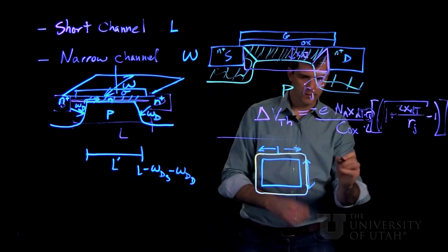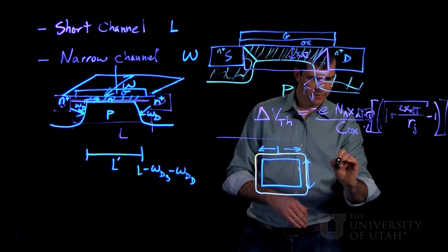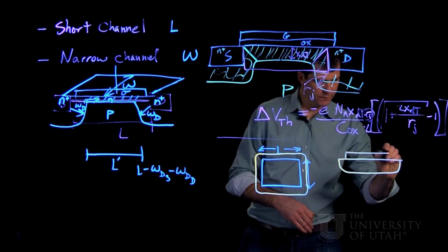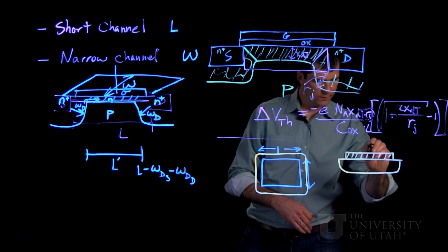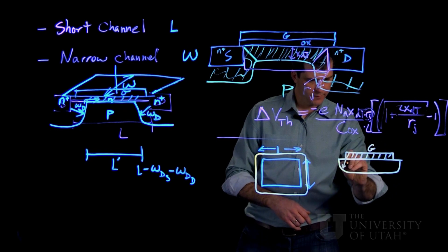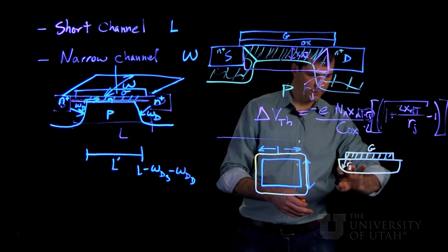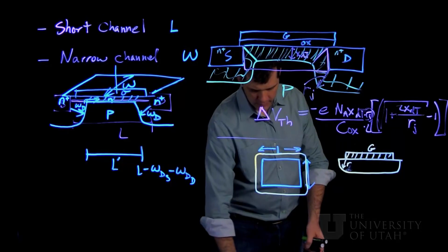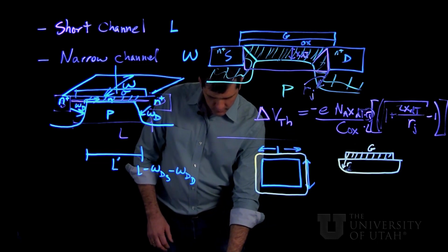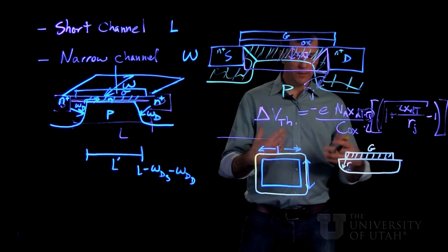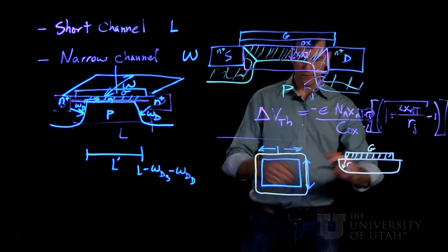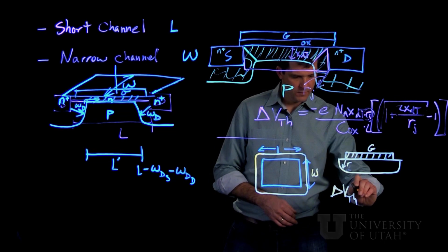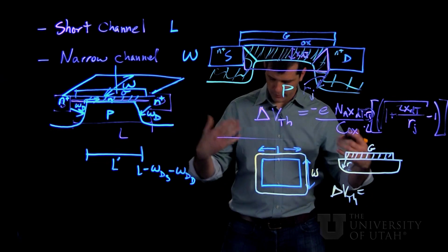And then if we view it from the side, cutting along the width direction, it'll be shaped something like this. So your actual physical gate viewed from the side looks like this. But the depletion width extends this distance R, excuse me, that shouldn't be a J, this distance R around from each edge. So again, making some arguments about the total amount of charge that the gate can control as a function of shrinking this width direction, you end up with an expression that the change in the threshold is now going to move in the opposite direction. It will be a positive shift.